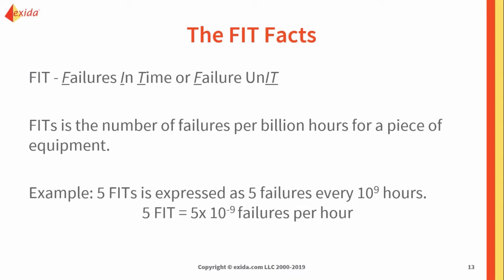Well, failure rates are commonly measured in the process industry, from the standards, in the unit of FITs. Depending on who you talk to, FIT could stand for failures in time or failure unit. I've seen them published both ways. But what a FIT is, is a number of failures per billion hours for a single piece of equipment. And as I said before, those failure rates or those FITs can be broken down into safe detected, undetected, dangerous detected, undetected, and even no effect and external leak failures as well.